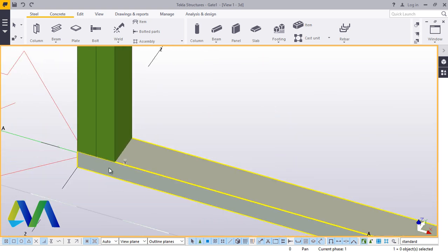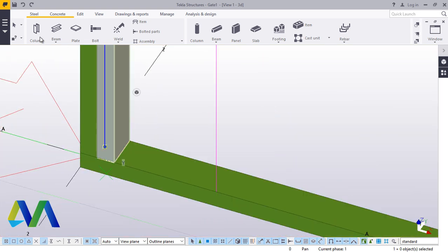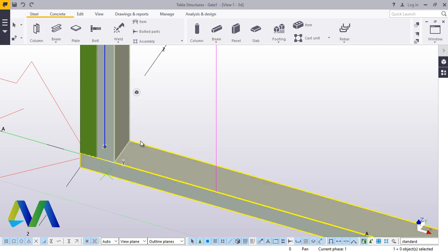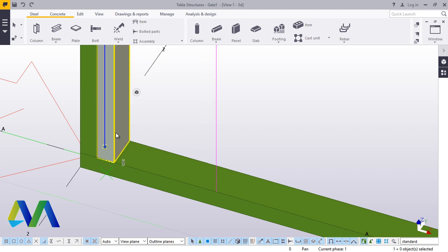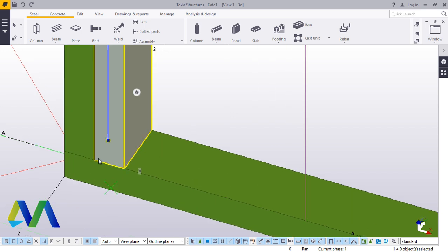In Tekla, the moment you've saved any change, you can't undo to go back to your initial setting. Once you've saved like this, I can't undo and go back where I was. You can only undo if you never saved what you are doing. That's all about it.